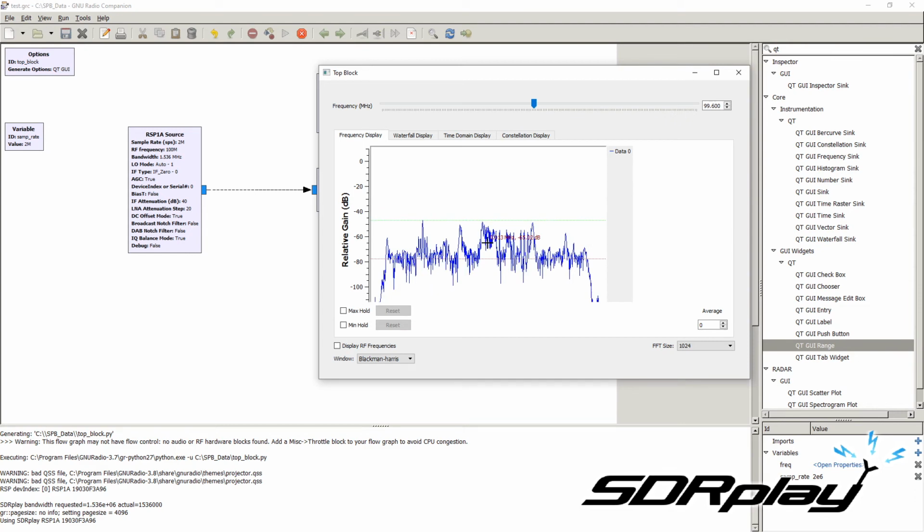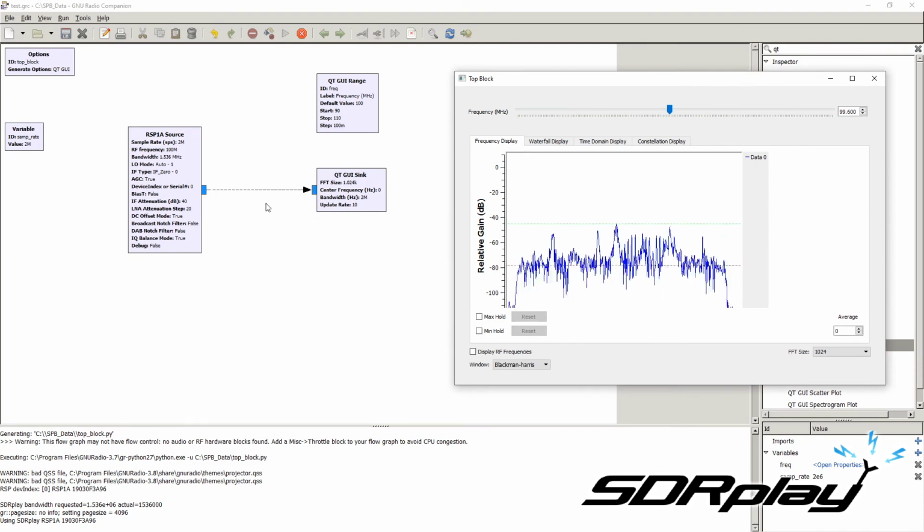If we want to receive this station, one thing that we'll need to do is ignore all other stations, because now if we were to demodulate the signal, we would demodulate the FM station, we would also demodulate all the bandwidth around this FM radio station, because these signals are present and will be demodulated by an FM demodulator. So we need to attenuate all the frequencies which are not the FM station we want to receive.